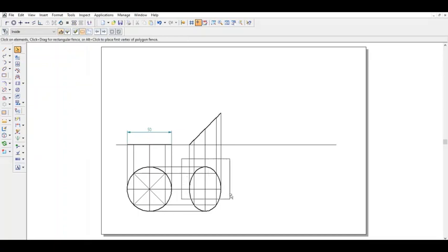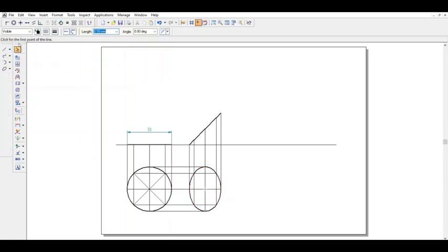And I also told you, when you select this, the internal portion of this particular ellipse, even this particular line, you have to draw it separately. Let me just redraw this. When you select this particular portion, the internal portion of this also must be selected. Why it must be selected is because in a circle you don't have any corners. To find out the points, suppose you are projecting it at an angle somewhere, so when you project this, you must find out all these points A, B, C, D and all those things. So to project that, you have to join these lines separately here inside this particular ellipse. I hope you are getting this.